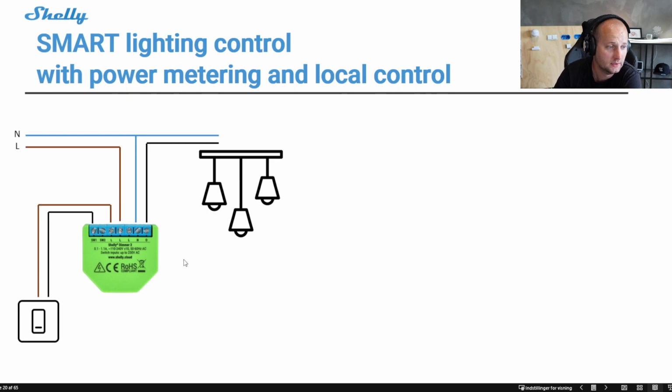So this is an example of the Shelly dimmer, and I'm using it in different ways in my own house. The idea behind the dimmer is that it has 2 inputs, which I think is pretty nice. Very often I'm just using the first input to control the light output. Adding a spring behind my wall switch gives it the button functionality.